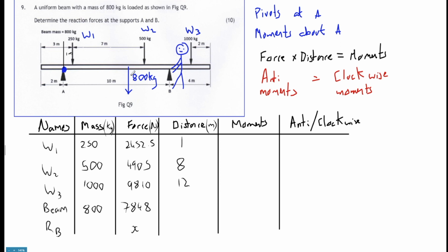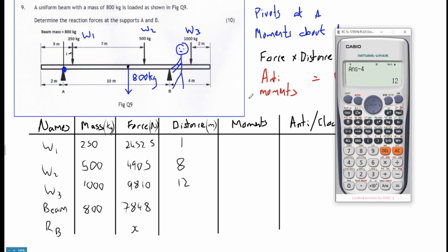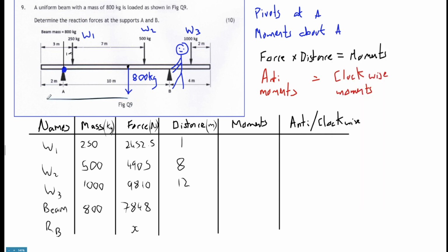The weight of the beam, we always take a load as a point mass. So I'm modeling this as exactly in the middle, the center of gravity of this thing. We just worked out the beam is 16 meters long. So this must be 8 meters from the edge. This will be 8 meters here.